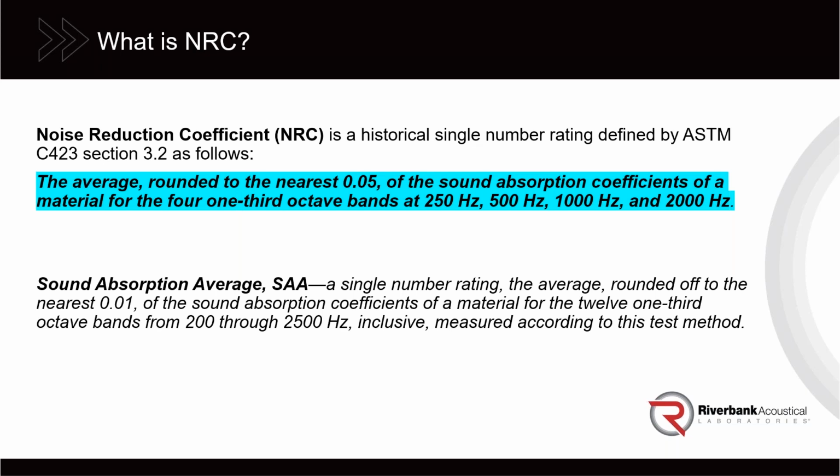Something similar happened on the transmission loss side of things. Recently, the International Building Code was updated where it defined the field test standard to be NNIC, and then suddenly everyone's asking for NNIC. So I think it's something similar to that. Once it's in those specifications, the manufacturers will fall in line.